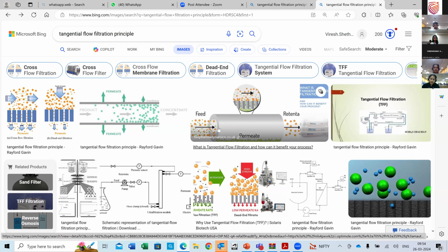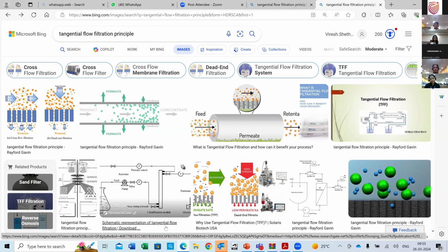So this is how the membranes will permeate. So you saw RO membrane in water purification process. So you will send the liquid in the space which is the hole on the fiber here, and then when the feed goes out, the liquid or the permeate or the material which can get filtered out will flow out from the sides of the membrane, and the concentrated material passes through. So this is tangential flow filtration. Now, where will you use it?